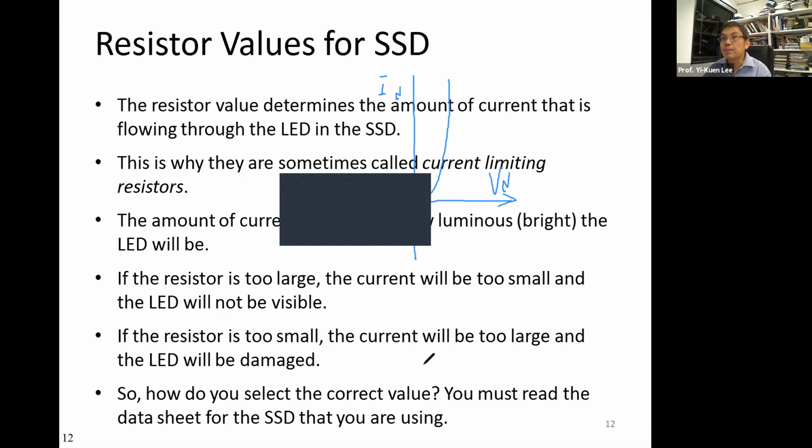Let me try to show you. Did you see this? Basically, this is a data sheet of the 7-segment LED display. You have 5611A and B. So what does it mean? The Arduino kit has this kind of code 5611A, common cathode, you see? And 5611B is common anode. So this can tell you quite a bit.